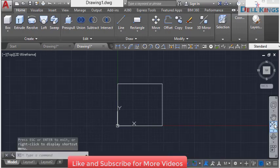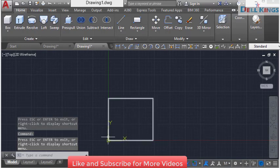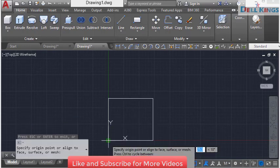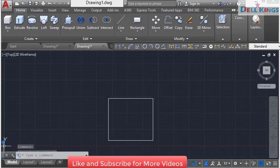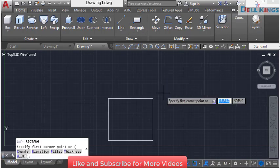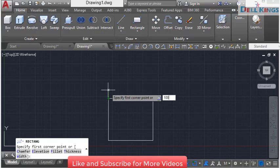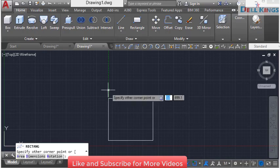So now you have this, and we can pan to bring this drawing this way. Now select this UCS and bring it to this side so that we can do our drawing neatly. Now select rectangle again, and at this point I'm going to give it an interior wall thickness of 100 mm. So type 100 mm as the extension and press enter.